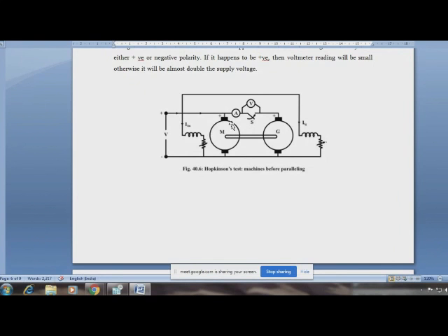Since we have two machines connected back to back, it's called back to back test. Regenerative because whatever the energy produced by the generator in terms of the EMF will be used to activate the motor, and whatever the torque produced by the motor is used to run generator. So in that way, the energy is regenerated. Therefore, it's called regenerative procedure. Is it clear? Any doubt here? Hello? No, sir. It's fine? Yes, sir.